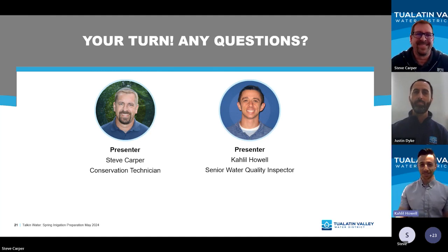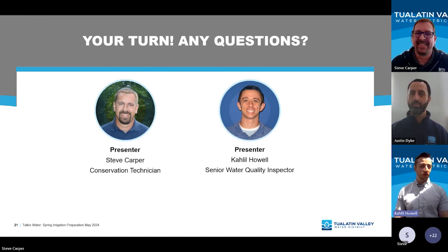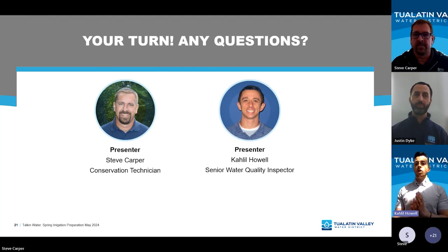It was for me, so I was excited to get to it. So outdoor faucets, per plumbing code, are required to have what's called a hose bib vacuum breaker on all threaded outlets other than washing machine hookups and boiler drains. So that includes those outdoor spigots. Now, those are not testable. I think in the late 90s, that was included in the plumbing code to require those hose bib vacuum breakers. So homes built prior to that year would not have them.